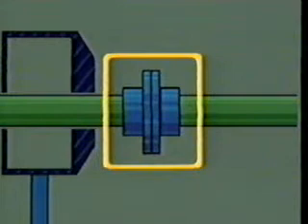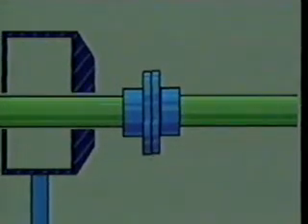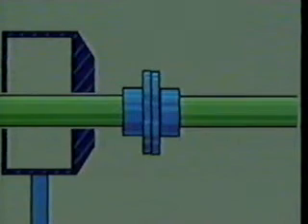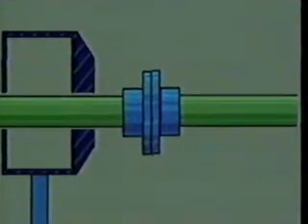You already know that on most centrifugal pumps, couplings join the shafts of the driver and the pump. They have to be flexible enough to handle misalignments between the shafts, as well as changes in the driver's speed. Alignment of both shafts is critical for good, smooth operation of the pump as a whole. If they're not aligned correctly, the shafts and other pump parts will vibrate.